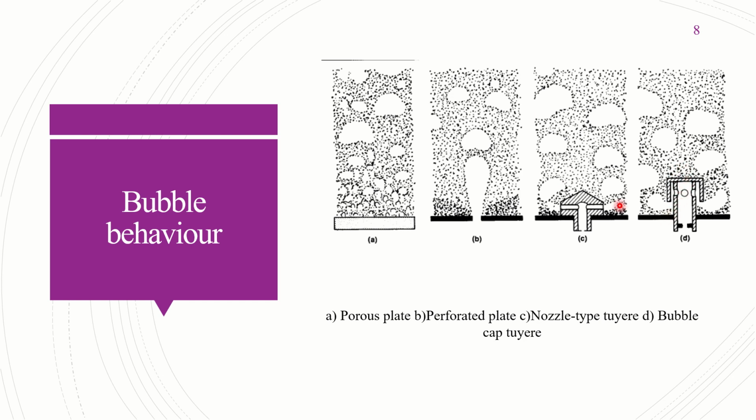So in general, above the porous plate distributor, the condition would be such that the gas velocity is greater than the minimum fluidization velocity, so many bubbles are getting formed. In other conditions, like in a perforated plate, we'll consider it as a single orifice opening. Here the minimum fluidizing velocity is maintained over this region, whereas in the center, the orifice gas flow rate would be very high.